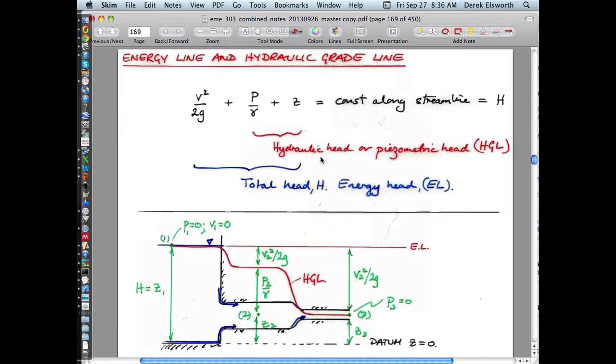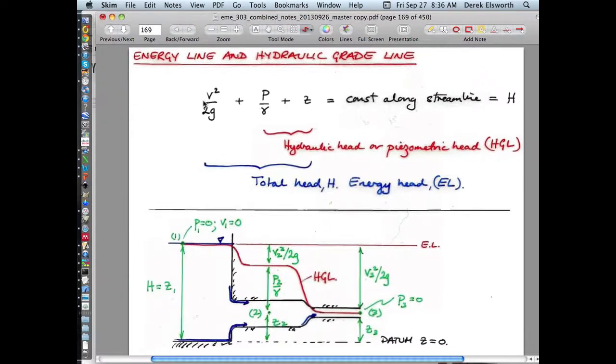So when you deal with fluid flows in porous media, you can use Bernoulli. The velocities are really small, and compared to these other components, we just ignore the velocity squared term.